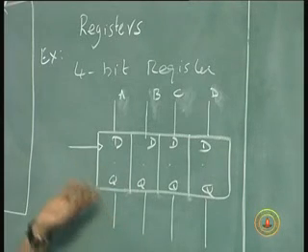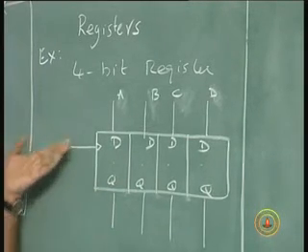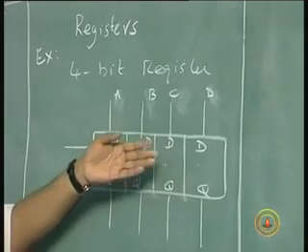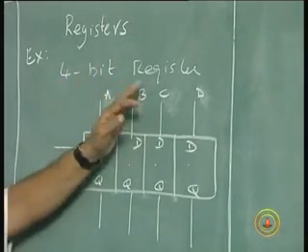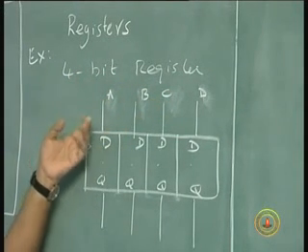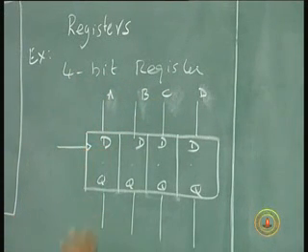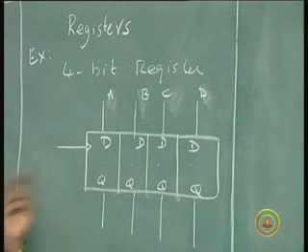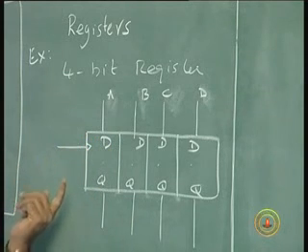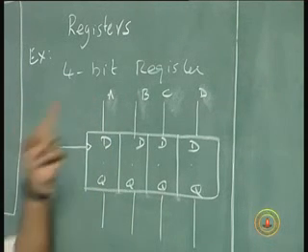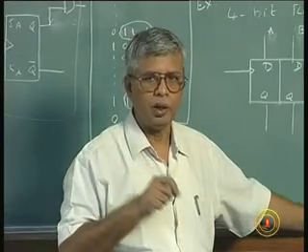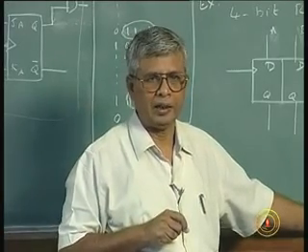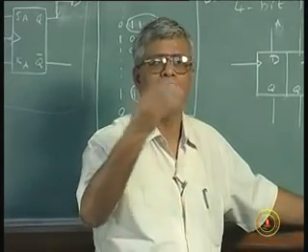Say memory. In order to get the input into the flip-flops or the register, you need to put the data that has to be stored on the inputs. When you clock it, these inputs get stored and they are available. But the problem with this would be what? The problem with this would be, I need to keep the data constantly here because the clock keeps coming. So you cannot design a clock for every little piece of hardware in your system you are designing, a subsystem you are designing. The clock is a common entity.